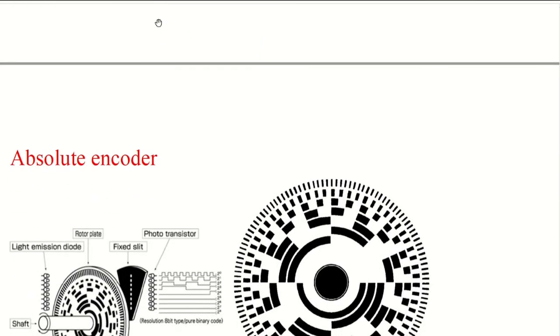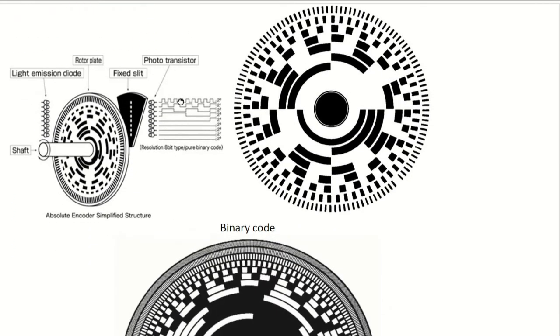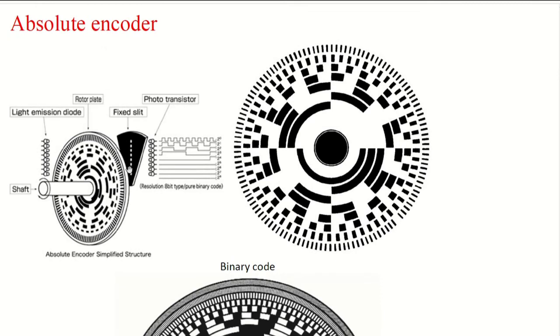So in order to get the absolute position, we can have another kind of encoder called absolute encoders. Here you have not only the incremental ones; for each LED you have a circuit. Here we present 1, 2, 3, 4, so 8 LEDs, so it's an 8-bit absolute encoder, and you have these 8 paths, as you can see, 1, 2, 3, 4, 5, 6, 7, 8.